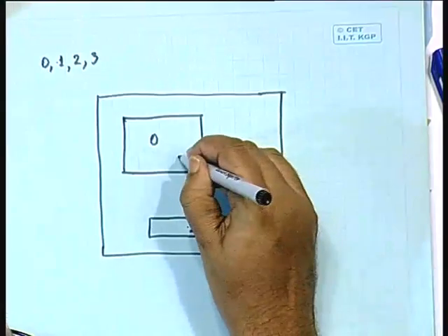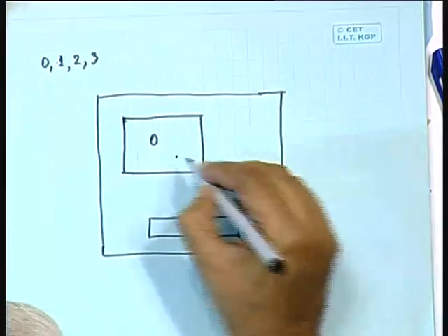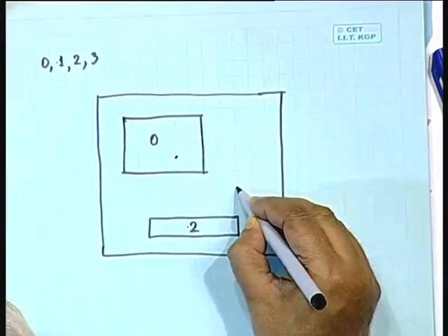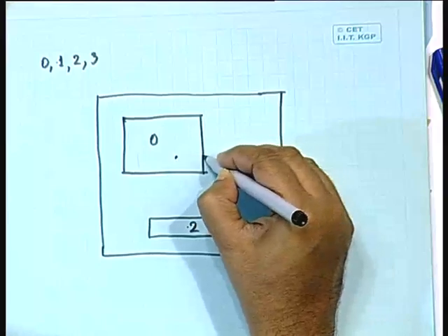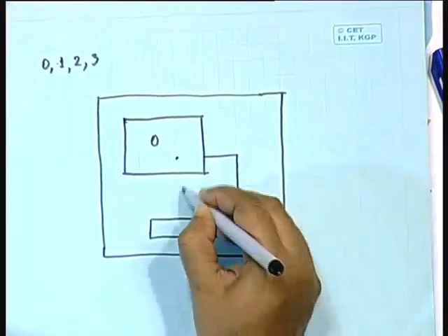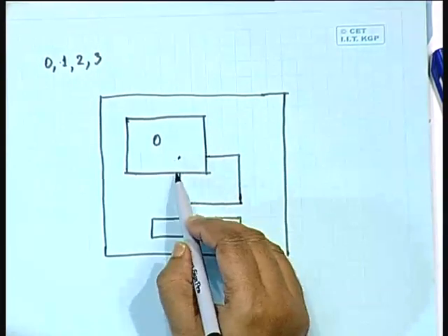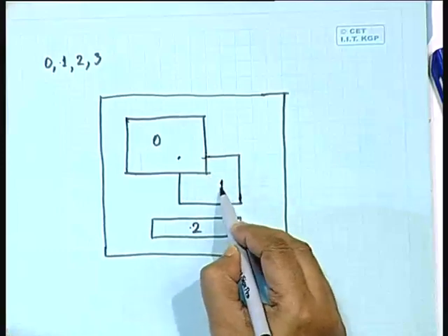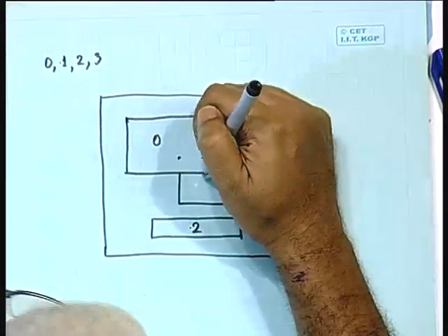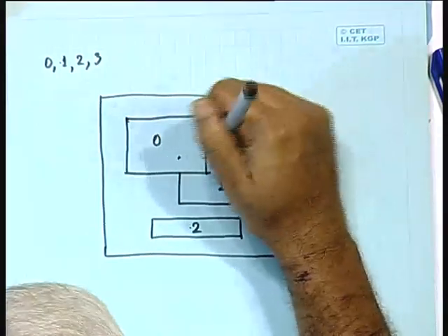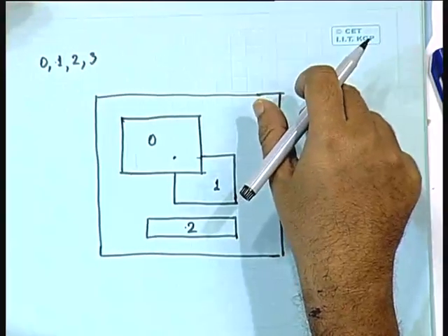While specifying slice group number 1, I specify the top left coordinate of the macro block here and the bottom right coordinate over here. Which means it is going to include all the macro blocks falling within this boundary, but what about these ones? These also come under group 1, but they are already defined as group 0 of the slices, and in fact the lower slice group number has the overriding precedence.